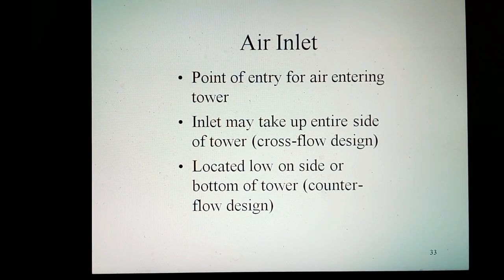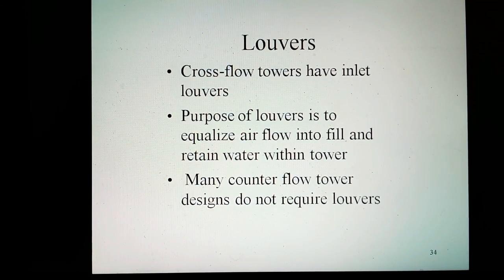Air inlet. This is the point of entry for the air entering the tower. The inlet may take up an entire side of a tower in a cross-flow design or be located low on the side or the bottom of the tower in a counterflow design. Louvers. Generally, cross-flow towers have inlet louvers. The purpose of louvers is to equalize airflow into the fill and retain the water within the tower. Many counterflow tower designs do not require louvers.